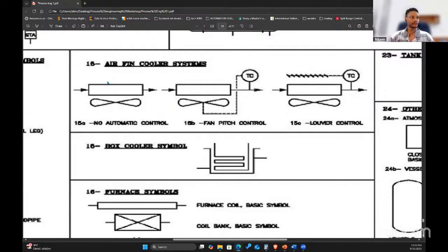Okay. So you have the process. This is the main process line. Remember the thick line, main process line going through the air cooler, and then the air is blowing, the air is cooling the process. For example, the process is going in at 70 degrees, and then air atmospheric temperature is going in at maybe 25 or even 30 on a hot afternoon. So you're using 30 degrees to cool this. Just like the way you have water of 30 degrees trying to cool something of maybe 100 degrees. Okay, so you use air and then you pull it down.